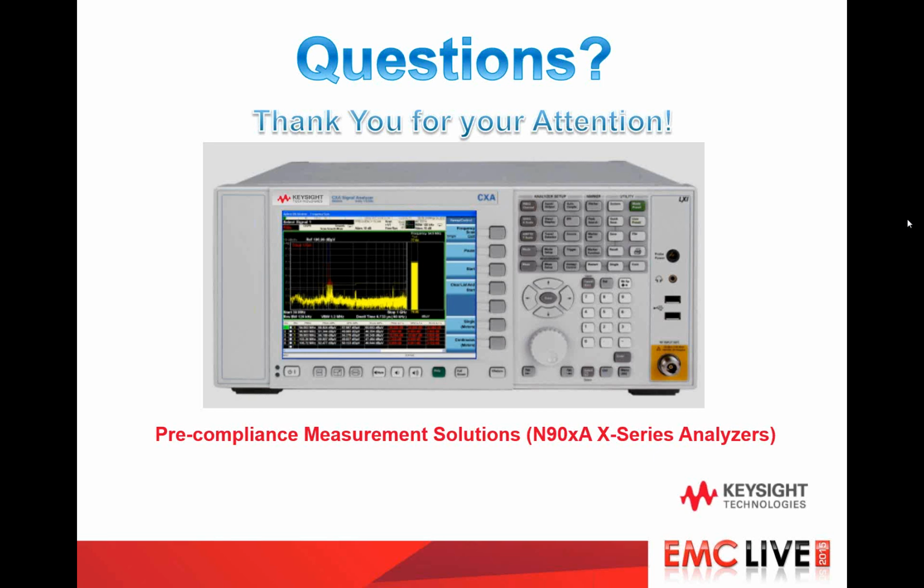Okay. Can you use a peak detector instead of a quasi-peak detector? You can, but as I mentioned earlier, the quasi-peak detector can actually identify true failures versus a peak detector. You may have a failure with a peak detector, but the quasi-peak detector measurement would say, okay, this isn't there long enough to cause a problem. The annoyance factor is low. So you could end up spending time troubleshooting signals that you shouldn't have to spend time on if you had a quasi-peak detector and used it properly.